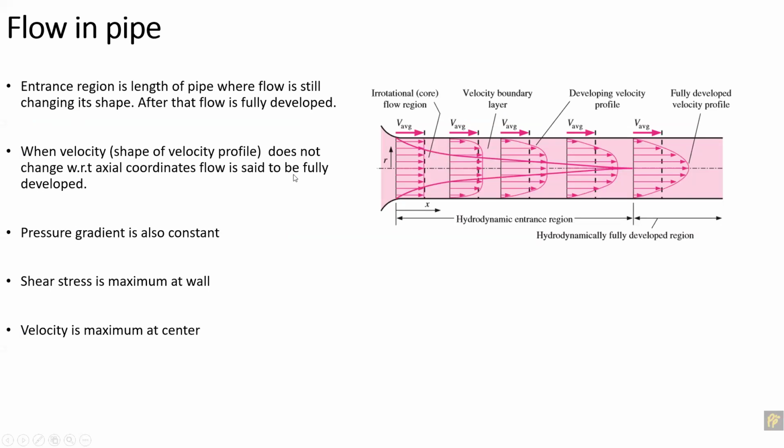Okay. So we must be looking at the entrance region when the flow is developing, and then the flow is developed. And please keep in mind that all the theoretical formulas, all the analytical formulas, are applied in the developed region. So in the developing or entrance region, these formulas which we'll see theoretically will not be applicable. And that's the point where we have the CFD tools, because CFD can predict this region, but the theory cannot predict this region over here.